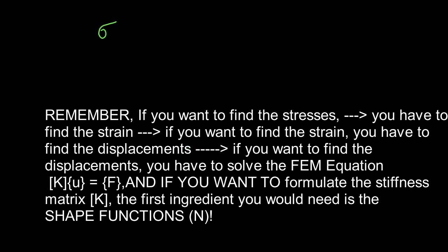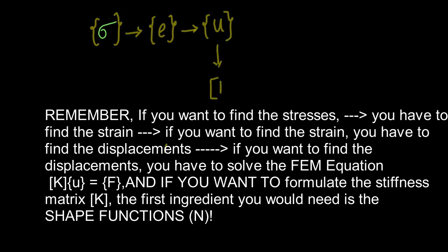Now, in order to find the values of stresses, you should know the values of strains. In order to find the values of strains, you should know the values of displacements, nodal displacements to be very precise. In order to find the values of nodal displacements, you have to solve the finite element equation, which is the stiffness matrix into U matrix is equal to the force matrix.